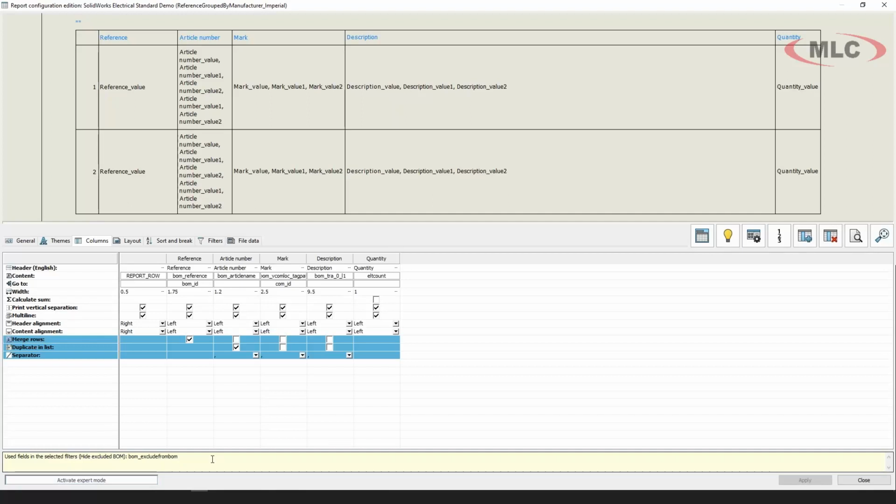I especially like the ability to just export real quick because you've got all your major components sized up, but you haven't got everything detailed out and connections made yet. Purchasing is like, hey, your long lead time items need to get on order soon. So I can export really quickly without putting any extra effort into it, exactly the columns they need. And then later on is when I'll actually get to that part of the drawing.